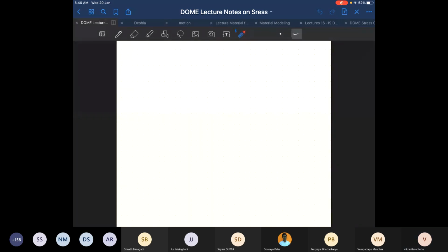Low carbon steel. Arey Baba, you are not there in any of the classes then. Like, which of the materials was being used in bearing application for rollers and raceways out of whatever I have just specified? So 52100. Very good. So 52100 steel was used for bearing applications. What was the strength of these steels? Do you remember? It was very high. It was close to 2 GPa, if you remember. Even 4000 series steels, after heat treatment, give you a yield strength of somewhere around 1 to 1.5 GPa.